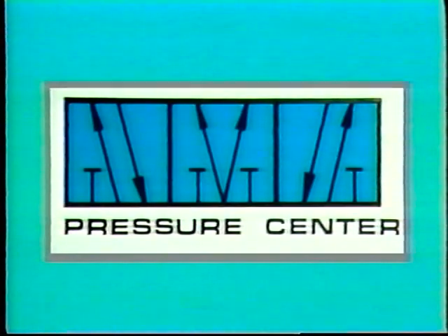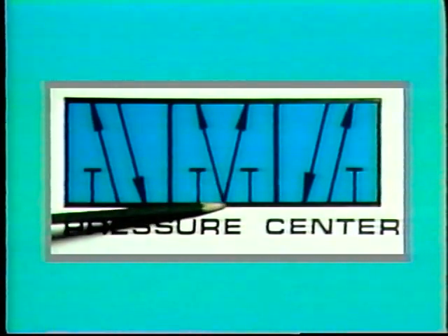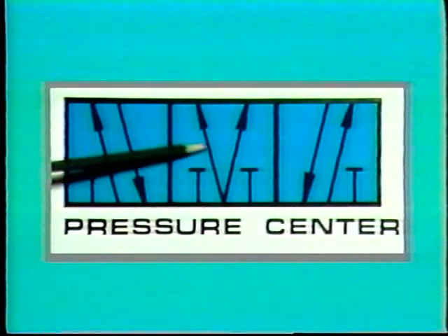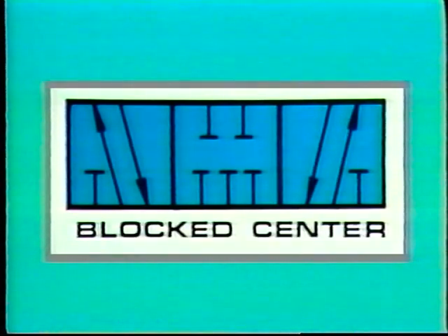This type of valve connection is called pressure center. In this case, when the valve is centered, both cylinder ports will be connected to the supply center. And finally, we have this case, where all valve ports are blocked when it is in the center position. What do you think this hookup is called? Blocked center? How'd you ever guess? Now, suppose we had an application where we wanted the rod to be free to move when the valve was in the center position. What valve configuration would you select to do this job?